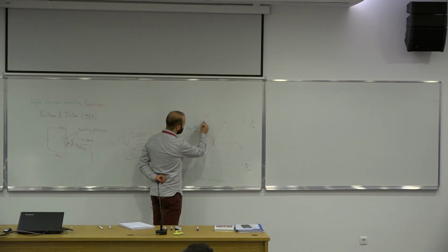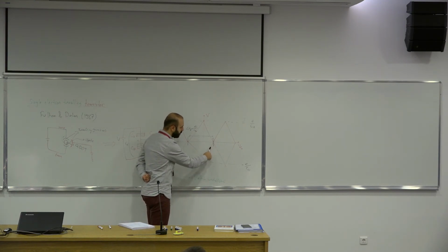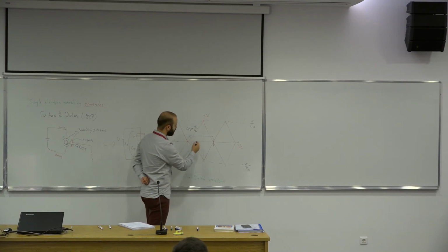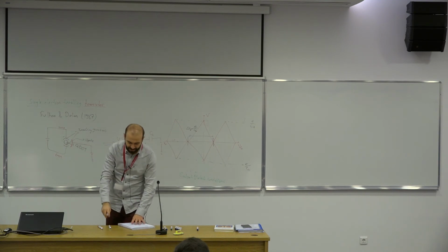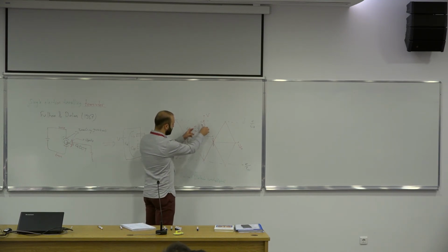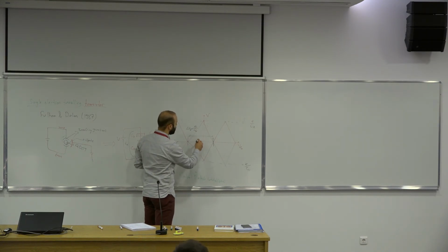Also if we solve the equations, we can figure out the slopes of these boundaries. So we can find the region where we got the Coulomb blockade established. So we can theoretically figure out the regions where no current will flow.